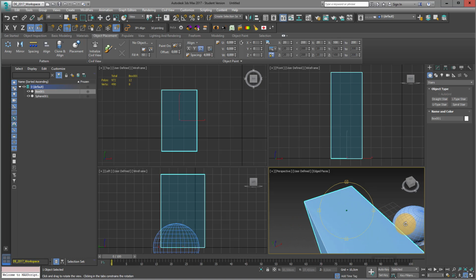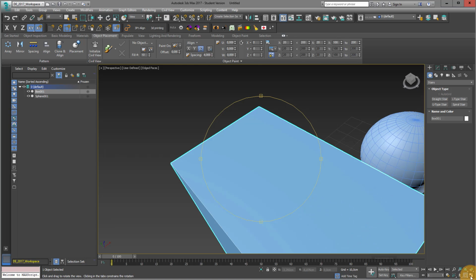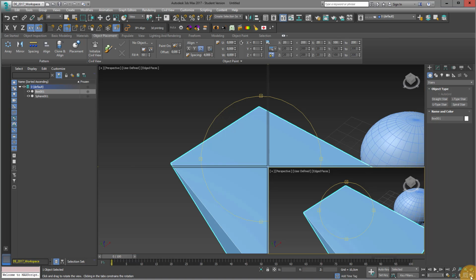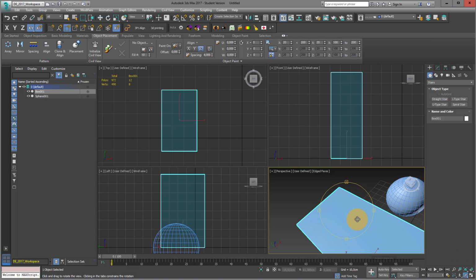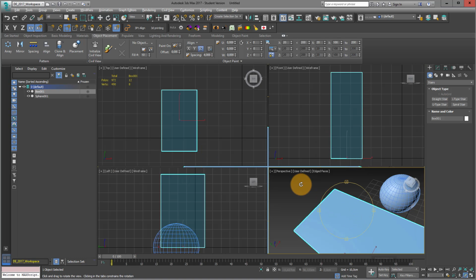The last button I use quite often, I already showed it to you. If you have selected, for example, the viewport, you can see it with the yellow line. You go to maximize viewport toggle, and so extend one viewport, and you can also go back, and you can also do it with the shortcut Alt and W. This is how you can change between the viewport settings.